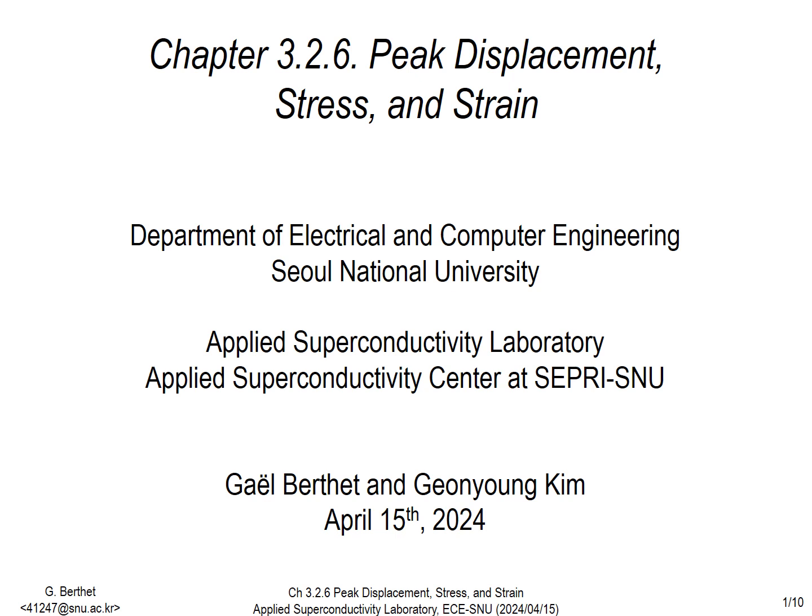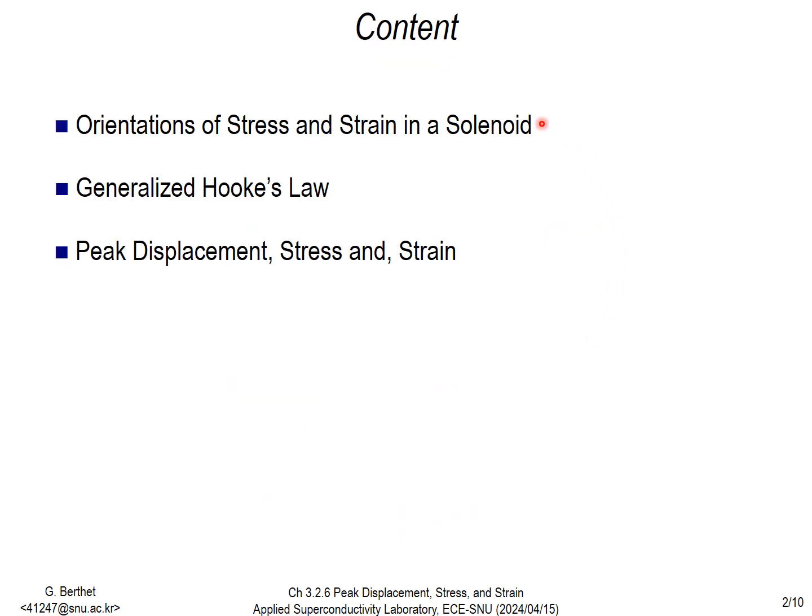Welcome back to the course on superconductivity. Today we're going to talk about peak displacement, stress, and strain. We'll first go over the orientations of stress and strain in a solenoid and then see the generalized Hooke's law. Then we'll define the peak displacement, stress, and strain.